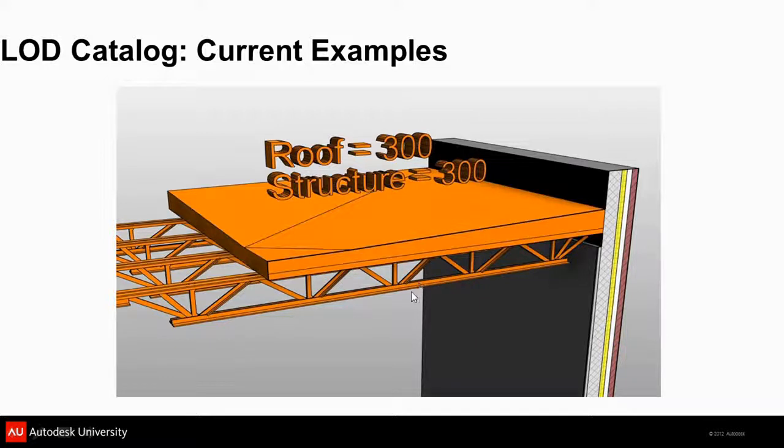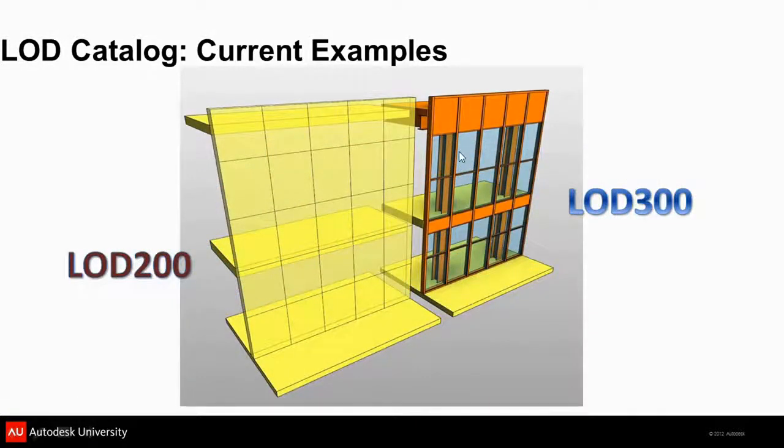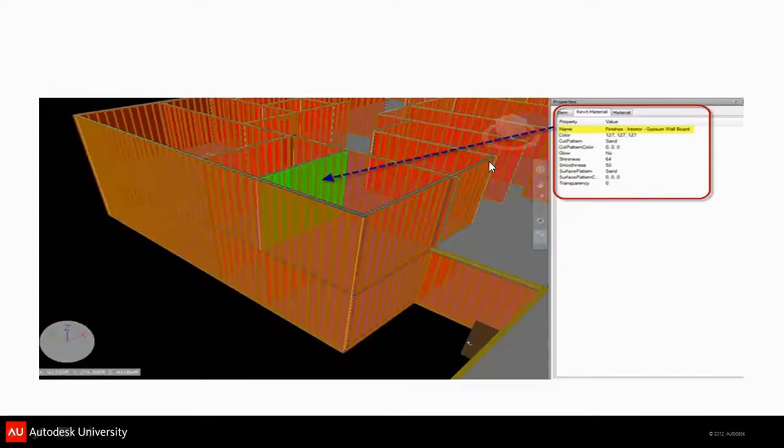Now, if you just need to know depth and slope, and you want to run your plumbing below, then the model's good for that, but not to actually go in it. When you start to look at the model where you have fritted glass versus clear spandrel glass, that'll start to affect what of your plumbing is actually showing through on the outside of the building. What considerations you have to give about what's visible. And is the glass that's supposed to be fritted and frosted really done that way? So then you would start to need that curtain wall in an LOD 300.